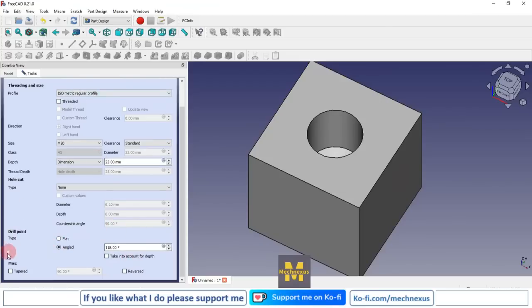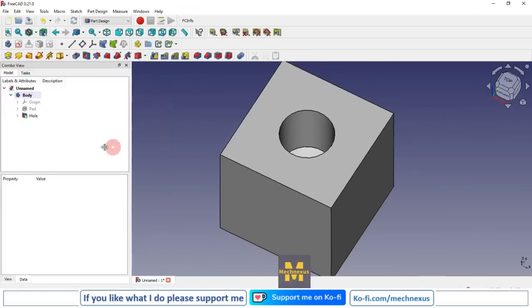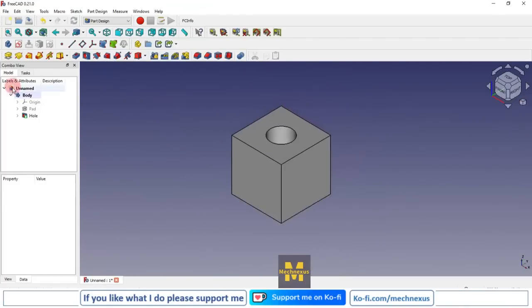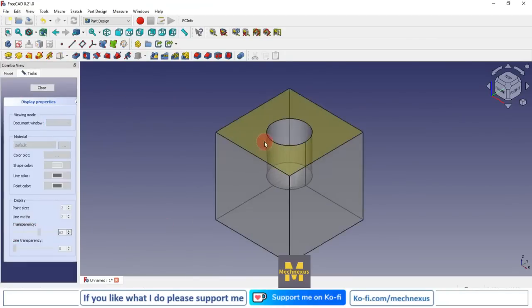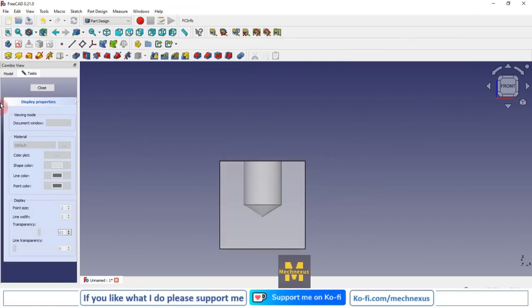Now we also have the option of the taper. If we increase the angle, then we can taper on the positive and negative side. Now we will click on OK. So here we have created the threaded hole of size M20. If you go to the body and go to the appearance section, and change my transparency, you can see that an M20 hole is created.